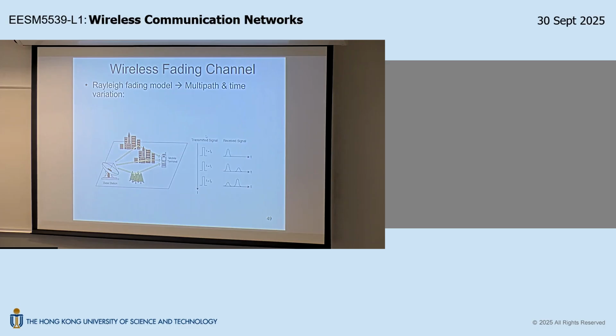So again, let's look at the nature of this shadowing. The dynamic range, the contrast on the y-axis between up and down due to the shadowing process by field test measurement is only around 8 to 10 dB. So it's not quite a high dynamic range process. And the time scale of variation. Again, do you think that this is fast or slow?